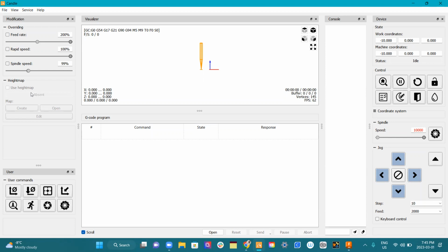There's different ways to clamp stuff down. So this here is a piece of wood with the clamps that are provided with it when you get this thing. This is called spoil board. It's just a piece of wood, and its intent is to be destroyed by this thing. When you want to drill something that is cut all the way through, imagine I want to make a gingerbread man. I'm going to want to cut all the way down and not just have a thin layer I have to get rid of later. So you tape it down to a piece of wood, you cut all the way through your material, and it'll still be stuck down. It will leave a score in this, but then you get a new one because it's just a piece of plywood.